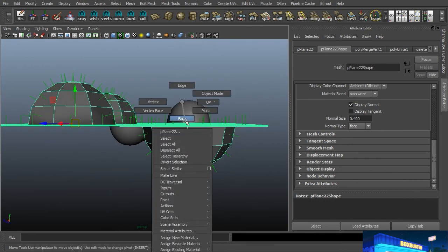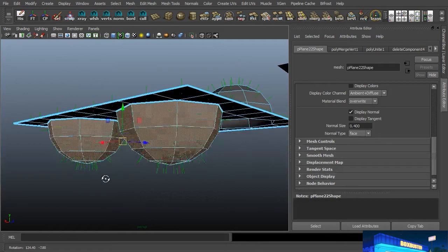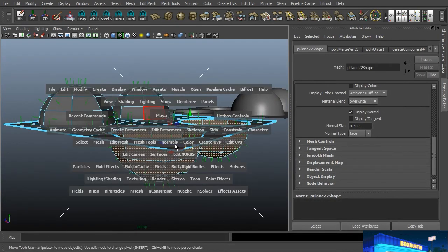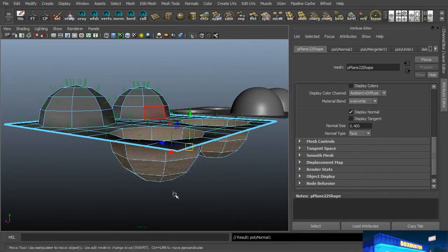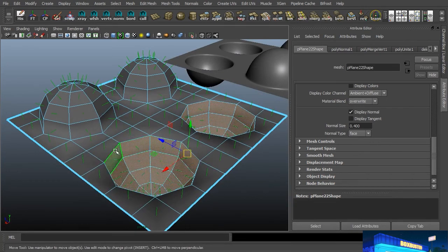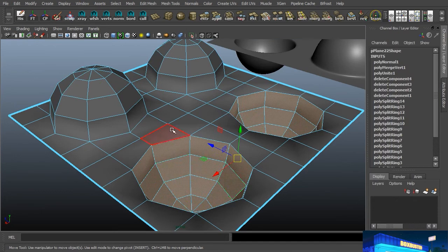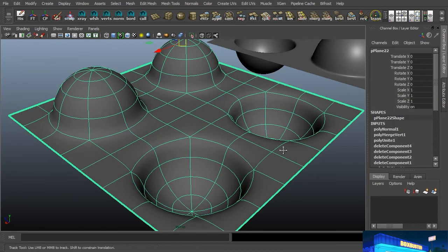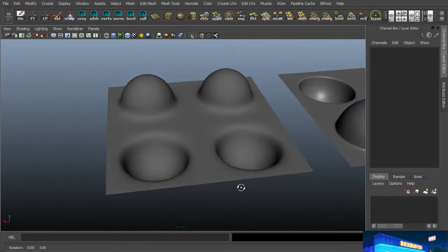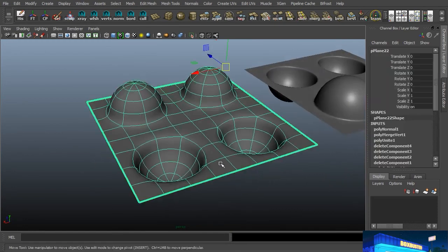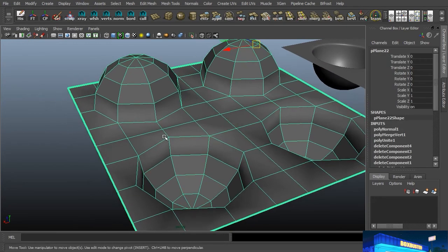And that's the information that we're using here. So we do need to go and grab all of these faces, and we'll go to normals, and we'll reverse those. And you can see that that border edge now goes away. So we'll click that and turn that off. And now everything smooths like it should. So that's good.